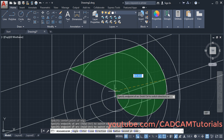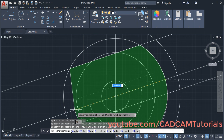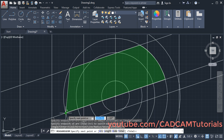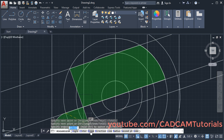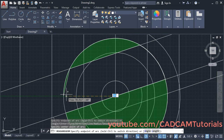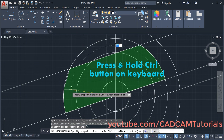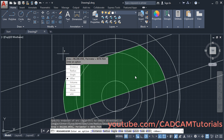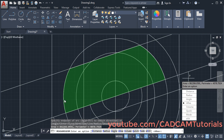Then I want to specify this line. For that click on this line, then click this point, again click on arc. Then again I will choose this center option, give this point as a center. Then again press and hold control to change the direction and click on this point. Release the control and press enter. So now here it is showing the area and perimeter for this marked shape, the green shape. Then to come out of this command, click on exit.